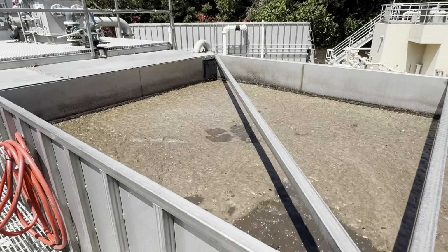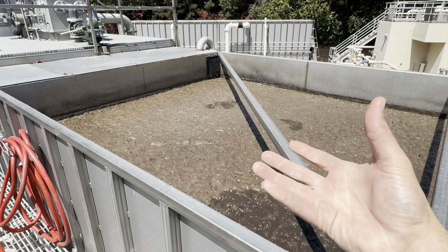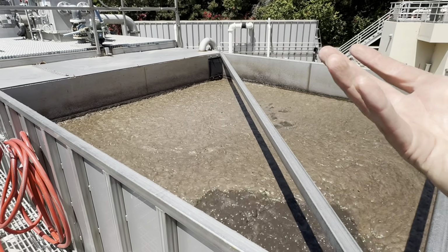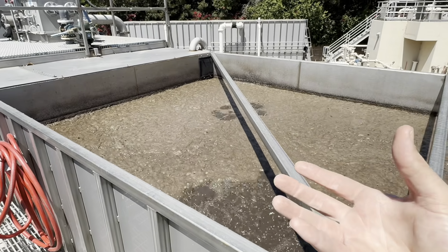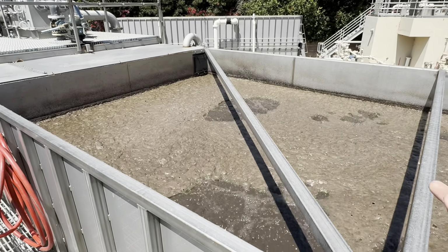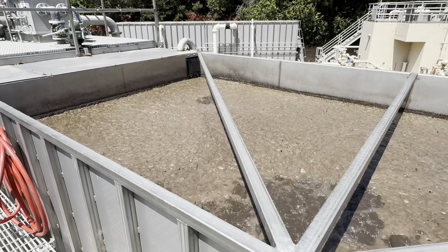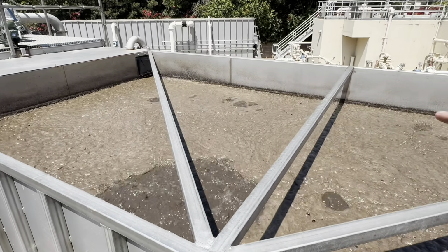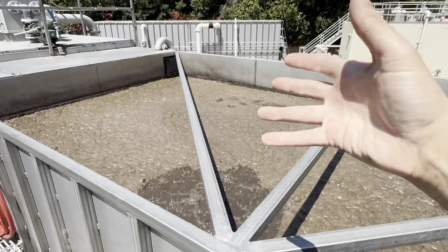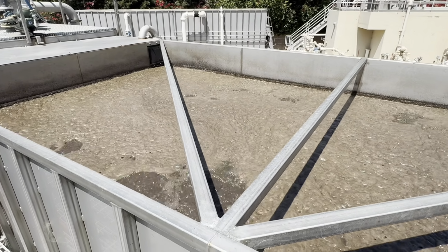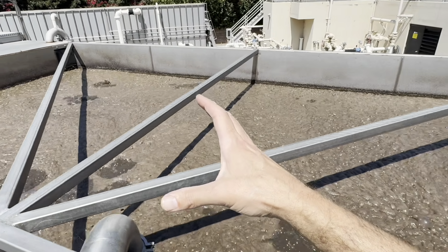So what we've done is we've farmed, in essence, these microorganisms, and they're going to consume that organic matter that has a BOD load to it. We're giving the dissolved oxygen to the microorganisms, and they exert the demand on this aeration basin, and they stabilize the wastewater, and they've eaten the food, okay? And so then they move over throughout.